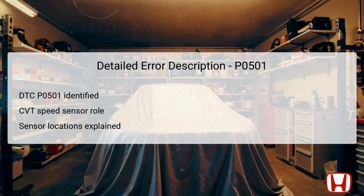The CVT speed sensor is typically located on the transmission assembly, specifically near the valve body. In most cases, it is mounted on the outer section of the transmission case for easy accessibility. The performance of the CVT speed sensor is crucial. If it deviates from the expected parameters, it can lead to erroneous shifting or acceleration behaviors in the vehicle. Thus, addressing this code not only involves inspecting the sensor itself, but also ensuring that all associated connections are intact, given its pivotal role in transmission control.